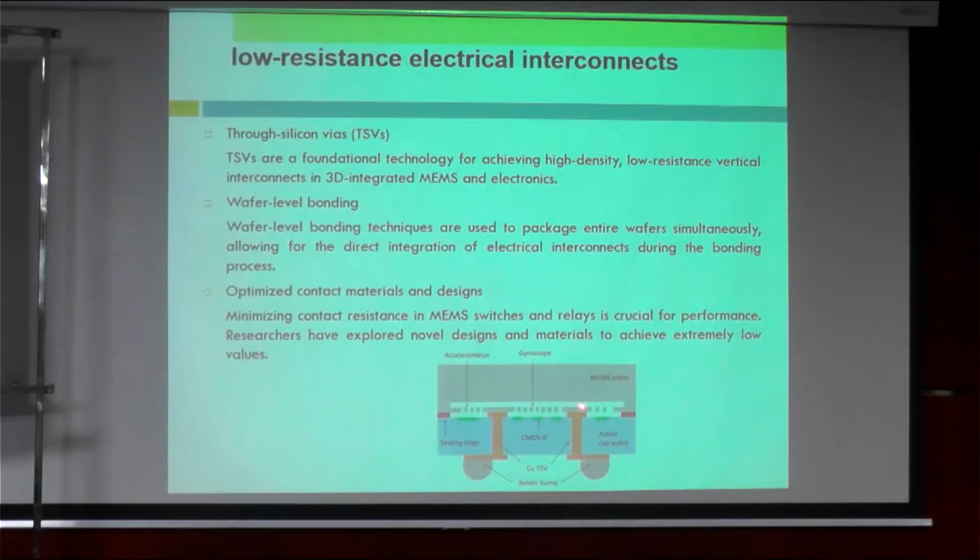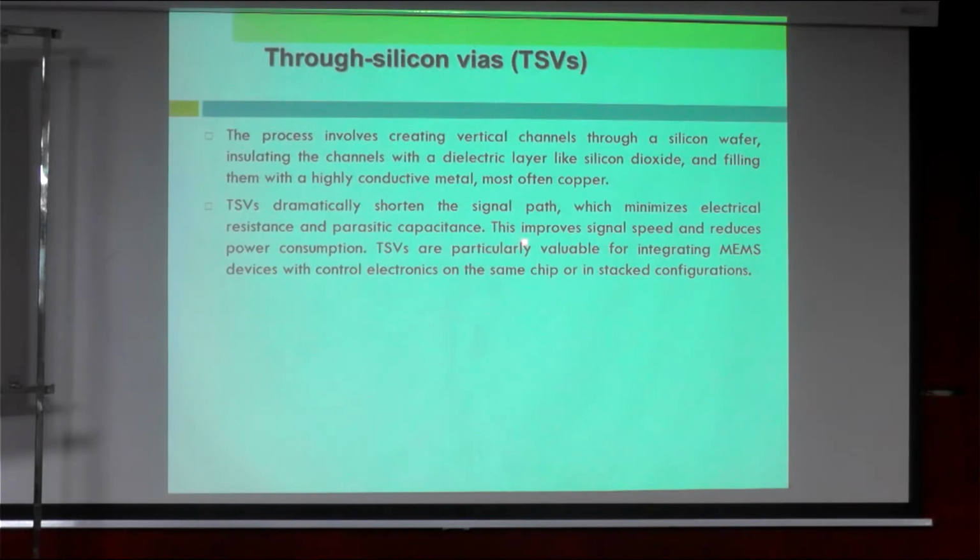If you see here, from here directly to the bottom, or to this component as well, rather than if you want to use wire bonding, the wire would go through the outside and will be longer. And this improves signal speed and reduces power consumption. TSVs are particularly valuable for integrating MEMS devices with control electronics on the same chip, or in a stack configuration. The stack configuration has made possible a lot of high performance devices.